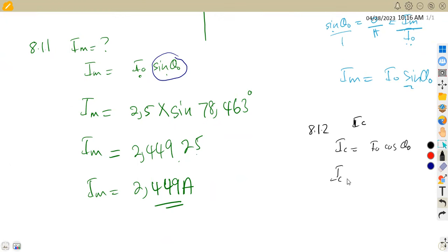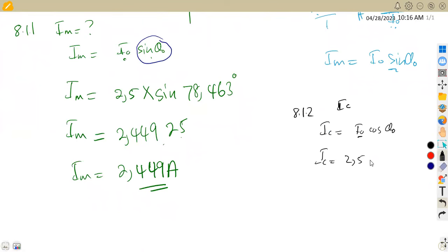And this is going to be 2,5 times the cos of theta. Remember, we said power factor is equal to cos theta. So this cos theta simply represents the power factor, which is 0,2. So we're going to multiply by 0,2. So meaning to say this is no load times power factor. We can simply use our formula like this. Okay, so this is going to give us 0,5 in amps. This is current, which is measured in amps.